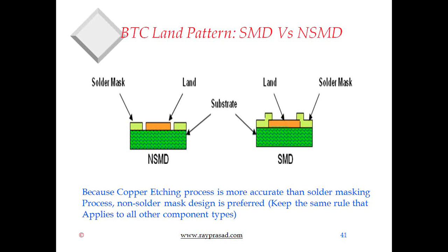other devices. That's the position that we have taken at IPC, meaning there is a solder mask defined pad that you see on the right where the solder mask goes on the pad, and then on the left the solder mask stays away from the pad. So in general, the guideline that we have in IPC for BGA, for BTC, for anybody else, is solder pad should be non-solder mask defined. Doesn't matter what component it is.